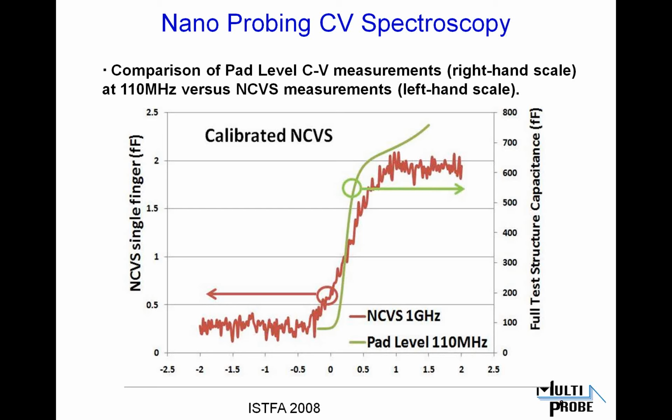But now you're able to do this in a way such that you can look at a discrete device, measure its capacitance, measure its neighbor's capacitance, and have some confidence that you're measuring an accurate number. And then furthermore, with some careful calibration relative to these sorts of test structures, you can actually calibrate the numbers that are coming out of the machine given a certain set of operating conditions.